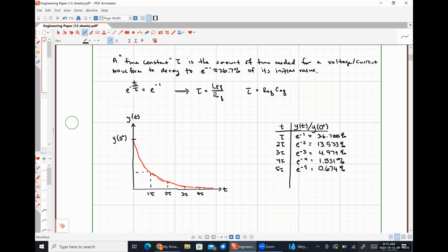And when we do our lab on Monday, you'll literally see what happens to your waveforms if you're operating your circuit at a frequency such that you're not allowing 5 time constants to occur. And you'll get these weird, funky looking shapes because you're not allowing your capacitor and inductors to fully charge and discharge during our cycle. Okay. So just trying to provide a little bit of context as to what t equals infinity actually means in the context of transient analysis here.